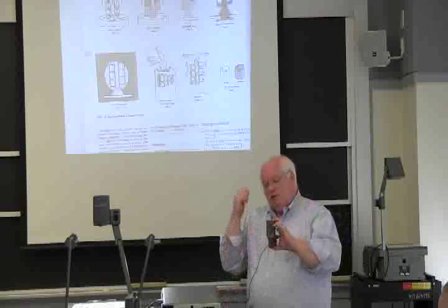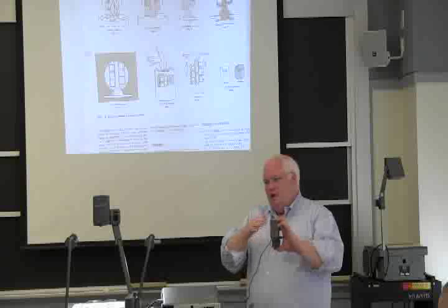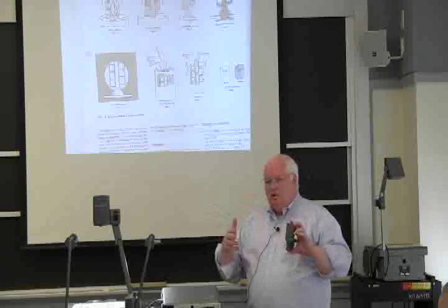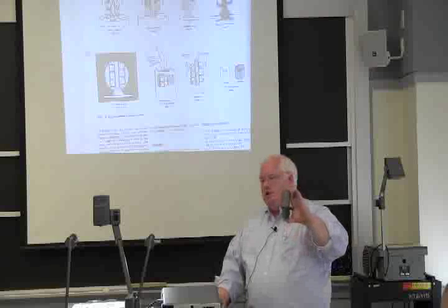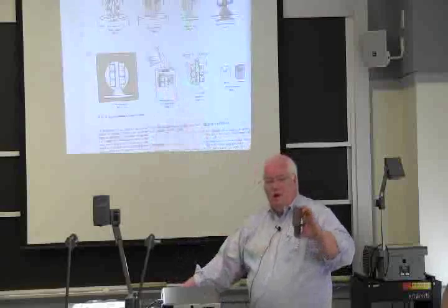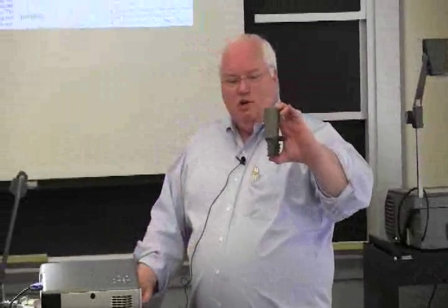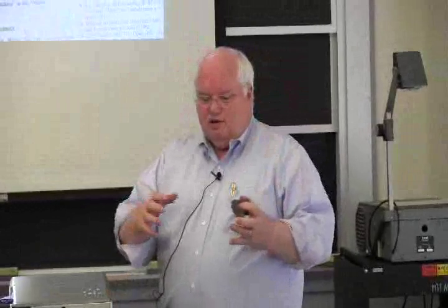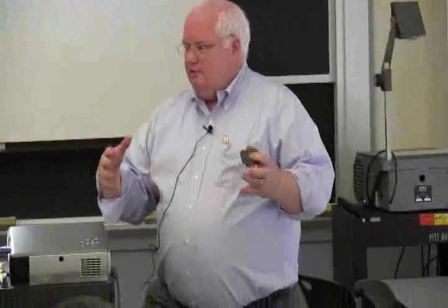But then they take that polycrystalline structure that has this shape, while it still has its core inside, actually in the investment casting, it's still got the casting around it, and they cool it very slowly in a temperature gradient furnace. So the furnace is about the size of this room, costs about $1 million or $3 million. You can make maybe 16 of these at a time. You see in this thing they're making multiple copies. Rolls-Royce makes 4 at a time. Pratt & Whitney and GE make about 16 at a time. Rolls-Royce likes to have better control in a smaller furnace than General Electric and the others, okay?